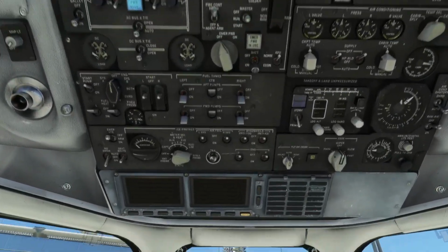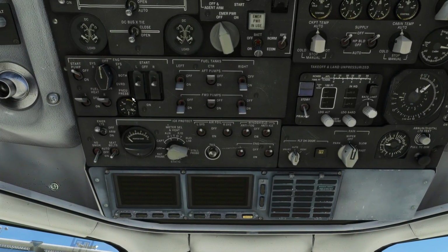Okay. Now, something you did notice, hopefully, from that diagram, was the one thing that the APU can do when you have those valves closed and you have air on and you have pressure here, is run the anti-ice stuff that runs off of the hot pneumatic air. So you're going to always want to make sure this valve is showing positive pressure if you're trying to run your anti-ice stuff for your airfoils.